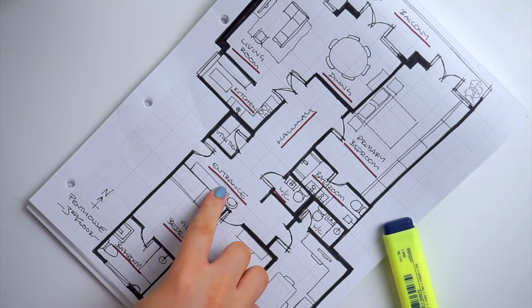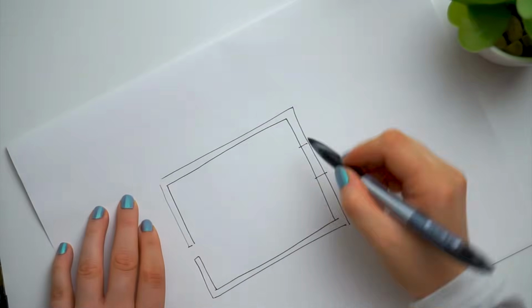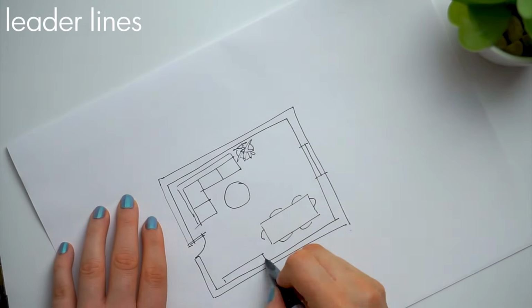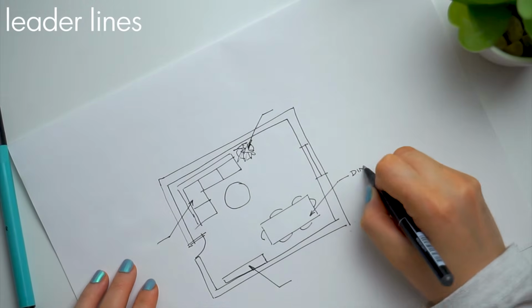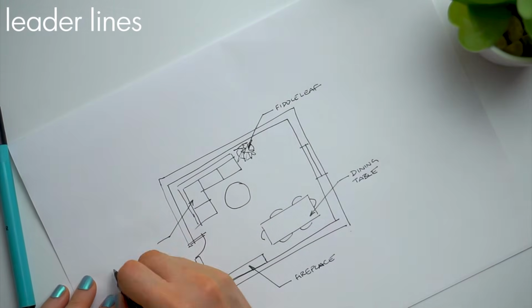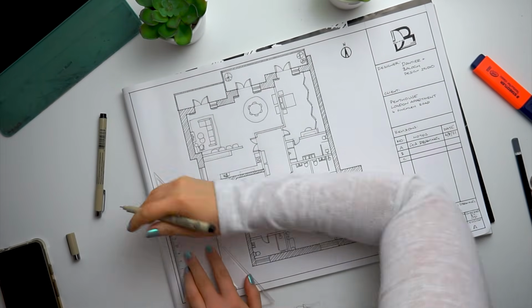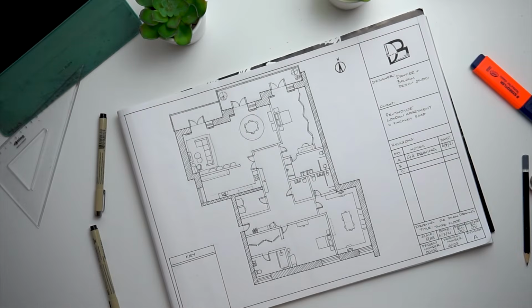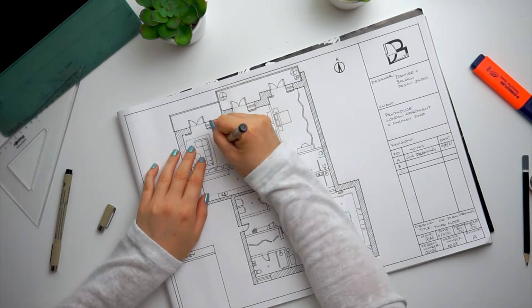And there are 3 preferred ways of doing annotations: simply by writing directly onto the space, or using leader lines, which are slightly angled annotations that connect to the plan. These are quite useful when the plan is small and there's not much to annotate, so that your drawing doesn't become too clustered. Or using numbers and then corresponding them with spaces in the drawing, like I've chosen to do today. And honestly, this is my favourite way to annotate just because it keeps the floor plan uncomplicated to interpret.